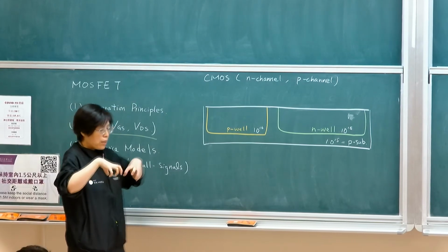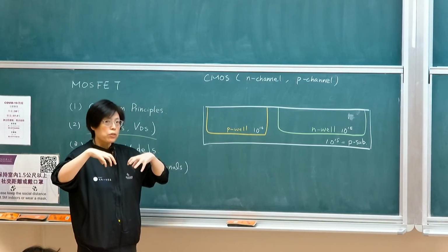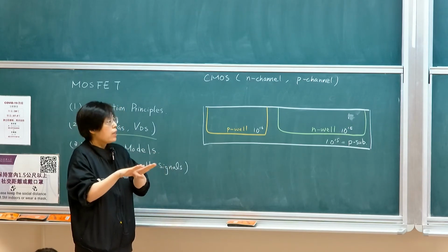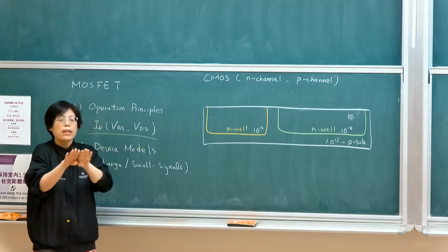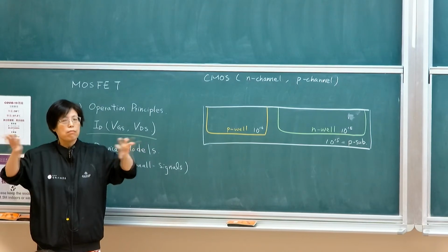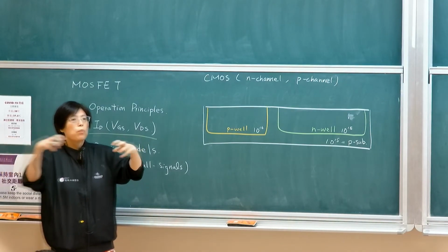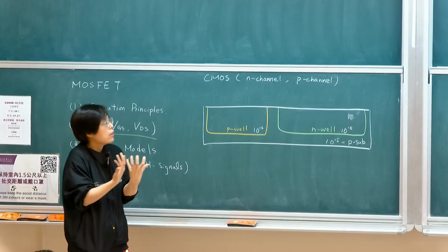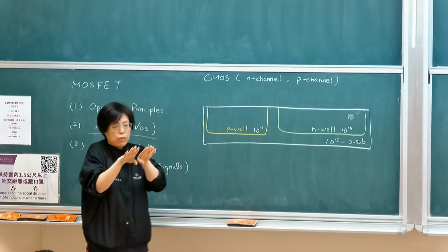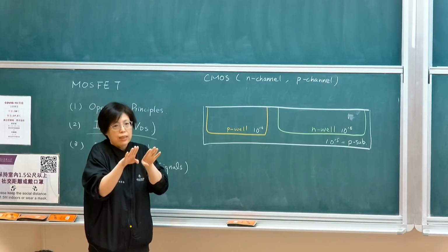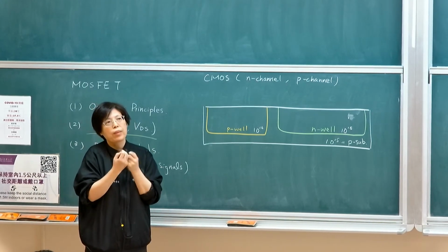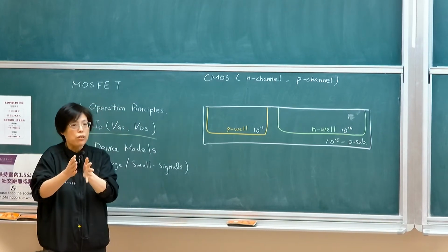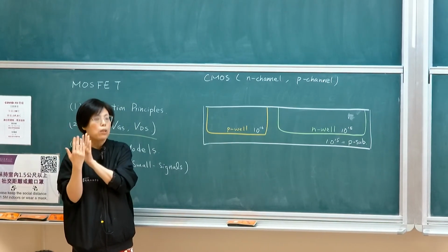Okay? And then in most cases, because my transistors are highly packed, if you simply leave your PMOS and NMOS with a space, they wouldn't touch each other because the junction itself is reverse biased. But if you want to pack your transistors very tightly, you want to make a wall between the transistors so that the isolation distance between you and me can be closer.